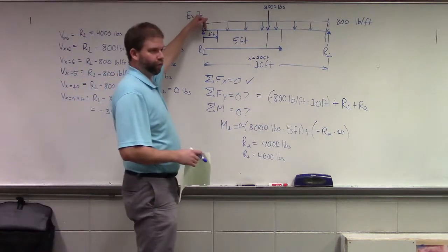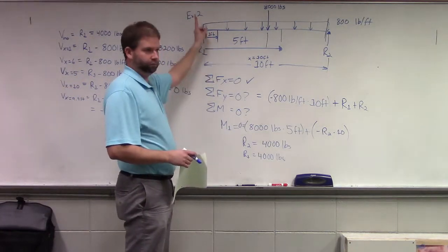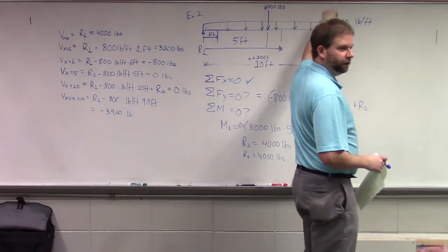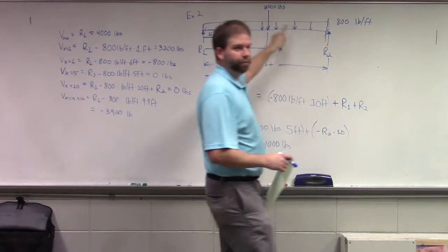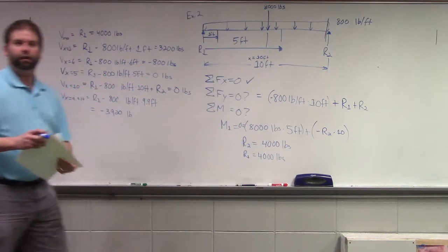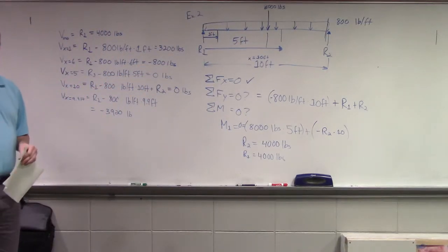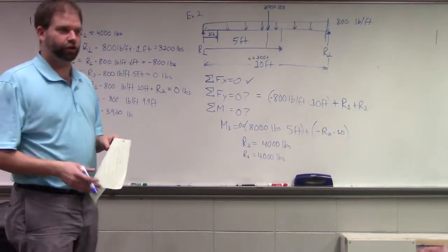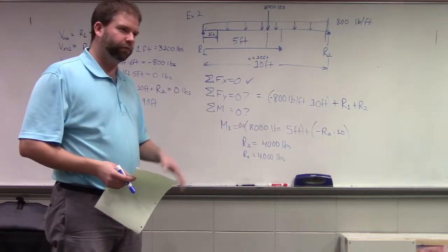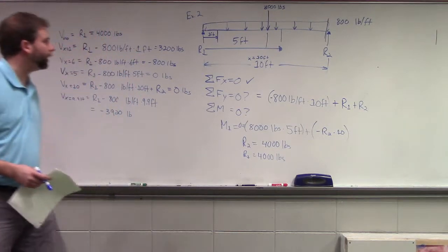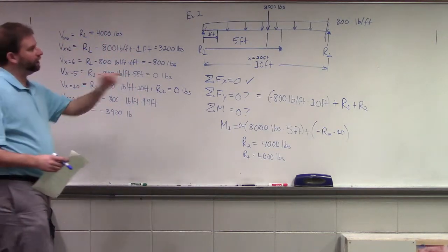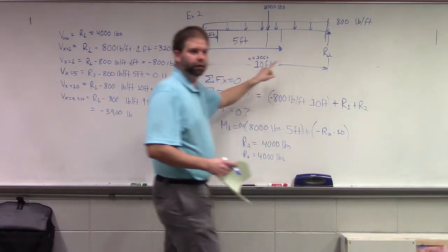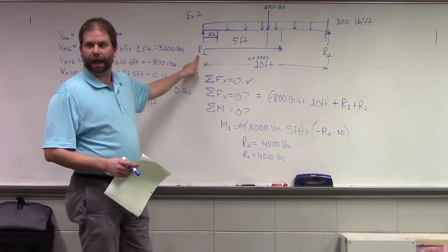Over here, the shear force is acting in this direction, right? Over here, the shear is acting in this direction. Does the beam care in which direction you're trying to shear it? No. It just cares how much magnitude you're trying to shear it with. Does that make sense to your question? Okay, so in this particular example, because our reactions are equal, the maximum shear occurs at both reactions.